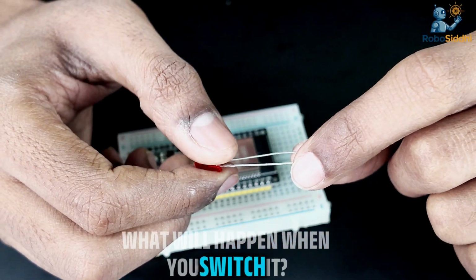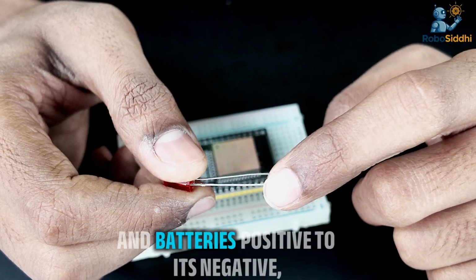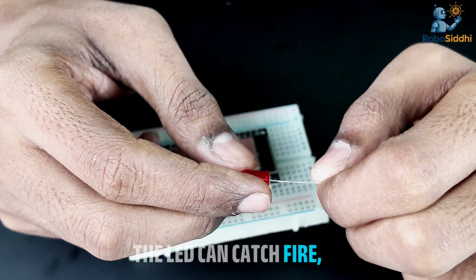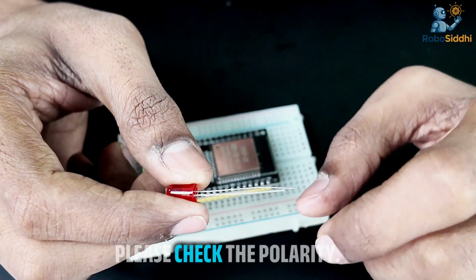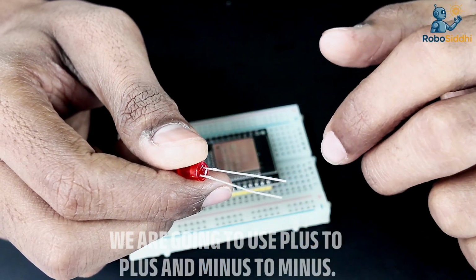What will happen if you switch them? If you connect the negative to the battery's positive and the battery's positive to its negative, the LED can catch fire, it can get damaged or it can burn. So to avoid it, please check the polarity. We are going to use plus to plus and minus to minus.